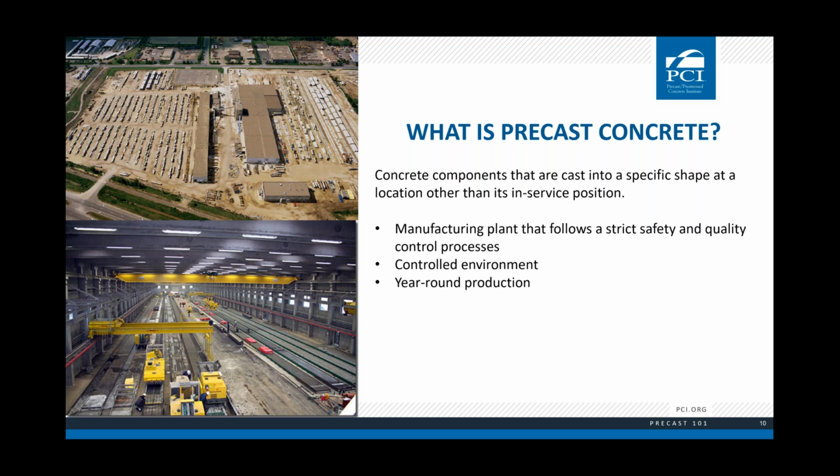So back to defining precast, right? I know I'm talking in a circle, but precast concrete is simply defined as a concrete component that is cast in a specific shape at a location other than its in-service position. For example, off-site in a controlled manufacturing facility that follows a strict quality control process. This allows for year-round production with very few interruptions to your project schedule.